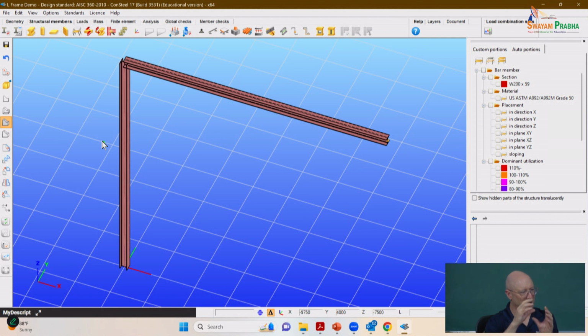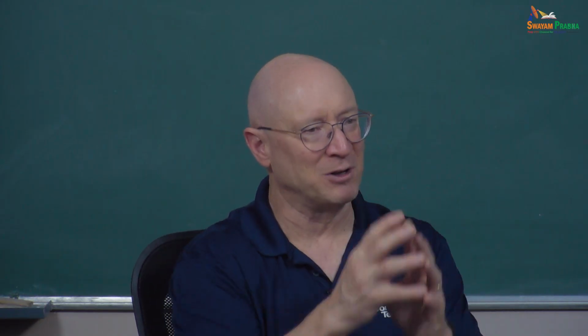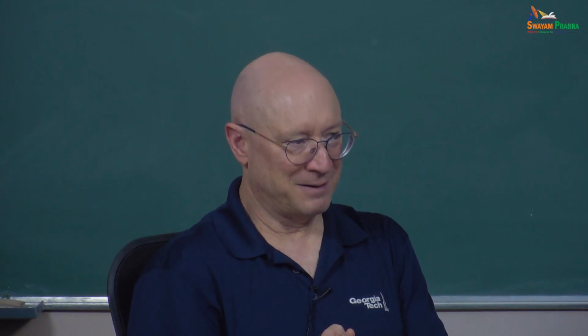Basically, the model covers different types of details at the joint: how does the warping continuity transfer through the joint? It's basically a thin-walled open section beam approximation of what you could get if you actually ran a shell finite element analysis at the knee. How critical is the warping degree of freedom in these calculations? Warping is essential when it comes to stability of thin-walled open sections. In the discussions we have had so far, we have not included it.